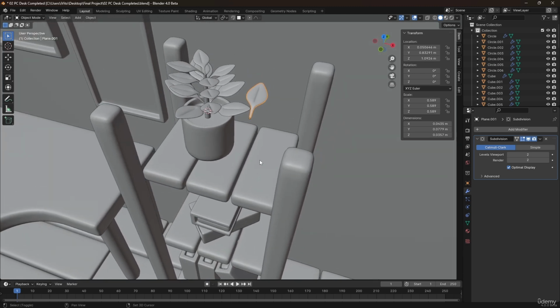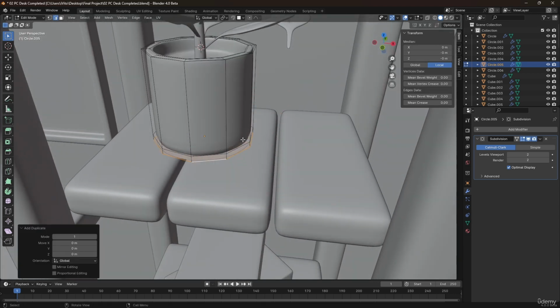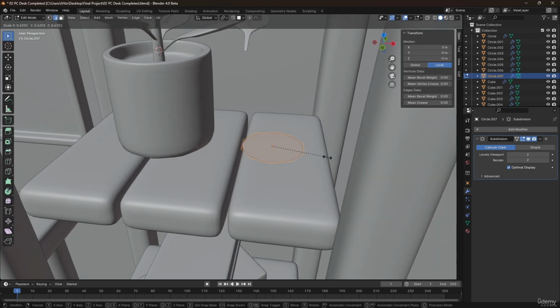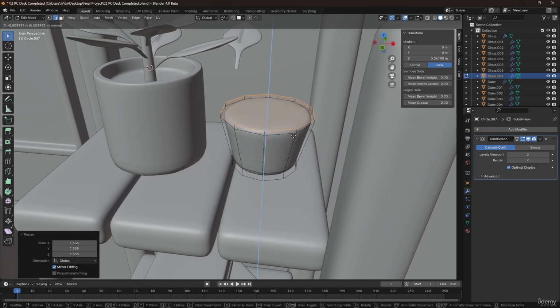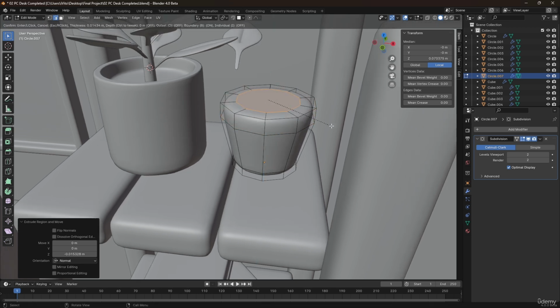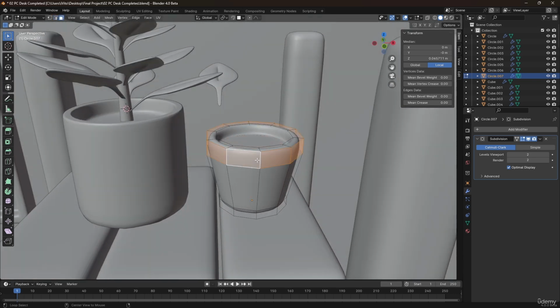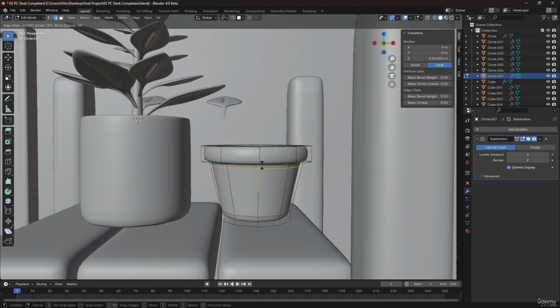And let's create a part here. And to do that, let's just take this edge loop. So in the edit mode, Shift D to duplicate. And then we're going to select that loop that we just copied. Scale it down. Extrude a couple times. And then we're going to insert the face. So we're basically just extruding and inserting face a couple more times like that. And then in the face selection mode, we're going to extrude these along the face as normal. And let's add a supporting loop cut there.